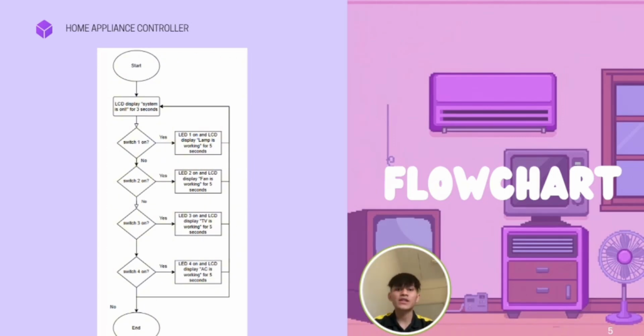For the second condition, if switch 2 is turned on and if it's yes, LED 2 will activate and update the LCD to display "Fan is working" for 5 seconds. If it's no, we move to the third condition.